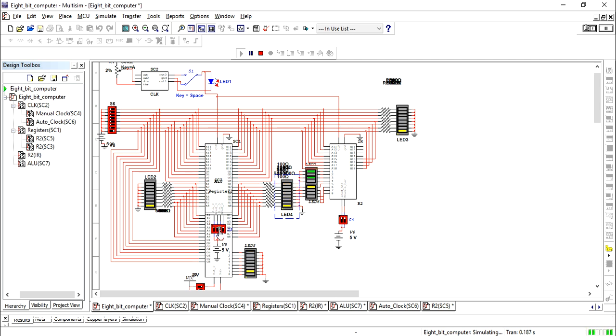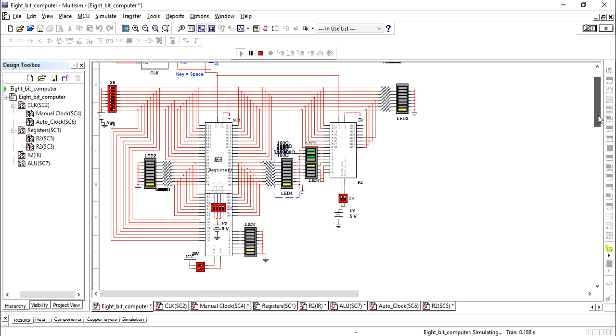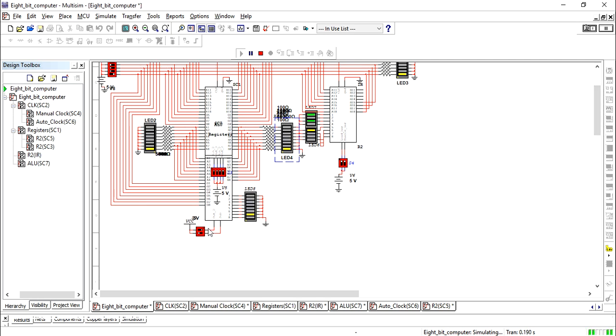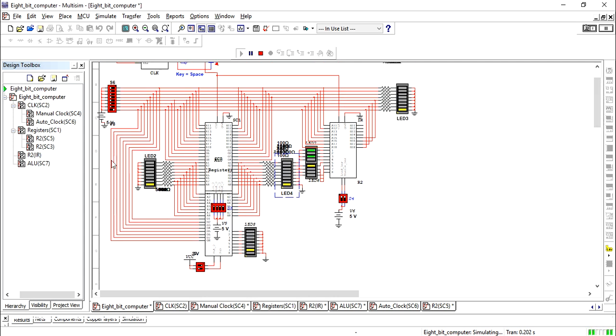Okay, one and one. Now I want to add two numbers. You can see the sum of these two numbers, one and one, is 10. So it is here. I will enable this out bar signal, so the sum of these two numbers will go to the bus, and I will enable the A in bar signal. So directly it will come to register A, and again it will be added. Again the sum will come to this ALU, and again it will be fed to the bus. So it will keep on going.